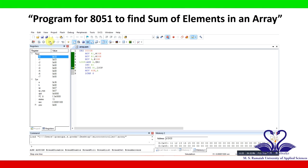Again it increments R0. R0 is incremented to 33 now. Then DJNZ, so R1 becomes 02. So it gets decremented. Then the accumulator gets added up. Whatever is the previous result, all these 3 numbers plus 14 will give you 4A.